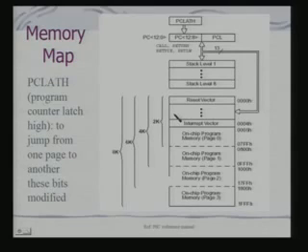Interrupt vectors are what? If an interrupt occurs, where the jump has to take place. So the first page is typically allocated for those purposes, and then subsequent pages are for on-chip program memory. Okay? So your program is typically stored in this area. And what is interesting is that this first part is separated out. Why has this first part been separated out? Because using this part, I can actually jump around to various locations with various kinds of constraints imposed.